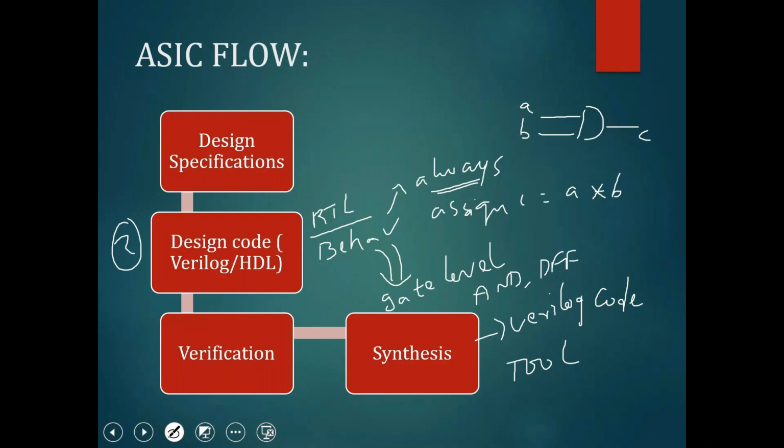You may have a question, why should we have a separate tool to convert this? Can't we sit and write it? Yes, it is possible to sit and write it also, but it is not possible for larger and complex designs. If I have 10 gates, or 10 flip-flops or 100 flip-flops, we can write it. But if I have multi-million flops, multi-million gates, how do I sit and write each and every instance and net connection? It's really tough and very difficult. So there is a separate team, a separate domain called synthesis, that can convert the behavioral code into the Verilog code.